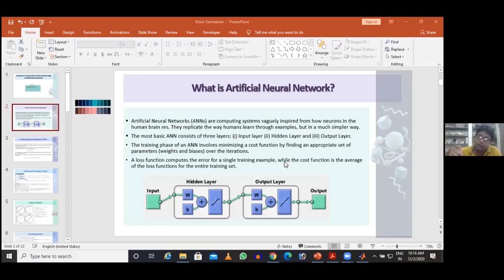The speed at which the stator flux is rotating is called the synchronous speed. From that, the rotor is getting magnetized. There will be some delay, due to which it does not exactly catch it. But if it is a permanent magnet, the rotor is already magnetized, no need to do anything. It is perfectly locked with the stator field, which is called a synchronous machine. Anyway, those are the different kinds of construction of the electrical machine. But today we will concentrate only on the asynchronous machine.